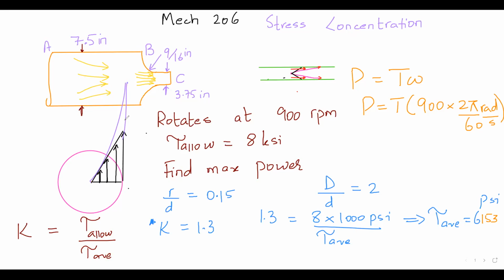Look, for example, previously I was putting a torque of 20 Newton meter. Let's say previously a simple shaft, very small value. I'm giving you an example, 20 Newton meter. I was happy. I'm within the safe limit. We are happy. Then suddenly for the same shaft, there was a change in the diameter. Then I kept on saying we can still use a torque of 20 Newton meter, and that shaft, let's say, breaks. This is a very hypothetical example. And I'm like, oh, come on. Just because I had a step, I still use the same 20 Newton meter of torque. Why did it break? Then one of you will tell me that now there is a step.